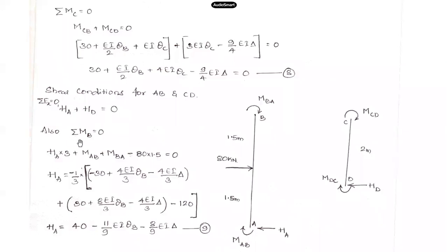Right now, what is HA? How to get this HA? I'll tell you the corrected values later. I'll give it when I give this PPT, and I'll explain that in one more class further. But now let me proceed here. HA plus HD should come out to 80. That is, HA plus HD should be equal to this horizontal force 80 kilonewton. Whatever horizontal forces are applied on the frame, you need to consider them. So from that I have to apply this shear condition.